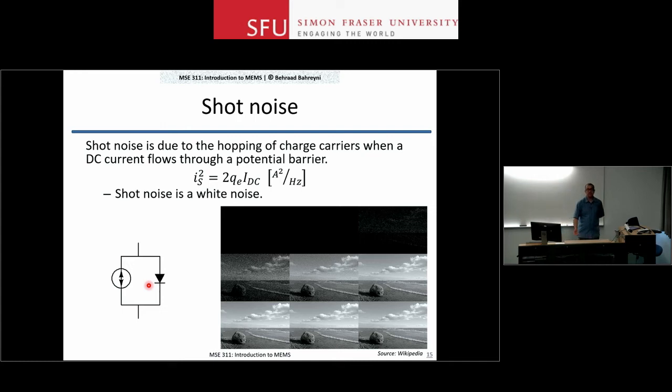And this is the implication of shot noise in a situation that a lot of you have seen. If you reduce the shutter time, you take a camera with a digital image sensor, and you play with how long your shutter is open, you get a result like that. So a really fast shutter opening time versus a very slow shutter opening time. Over here, you give the sensor enough time to average out the noise. Over here, you basically do not have enough signal, it's just noise. And you see that graininess in the image. That graininess mostly comes from shot noise.